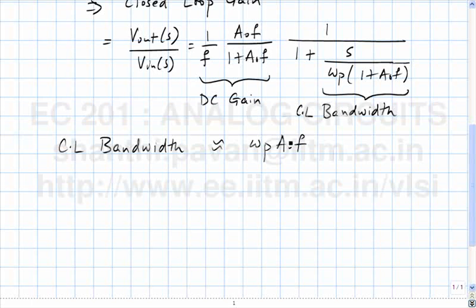Typically we think of an amplifier as being completely useless beyond the 3 dB point, but in this context you see that the forward amplifier still works as long as the gain has not yet reached about unity. Is that clear? At what frequency does the forward amplifier have a unity gain?